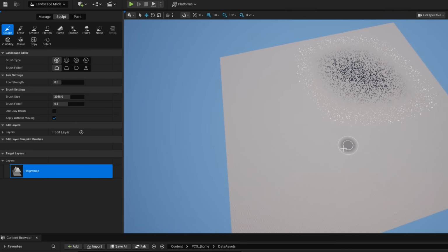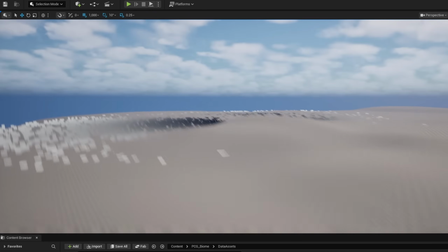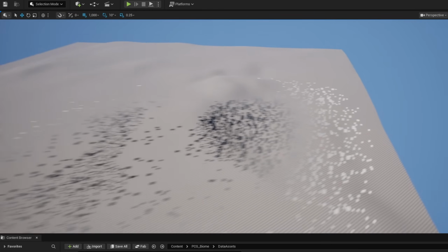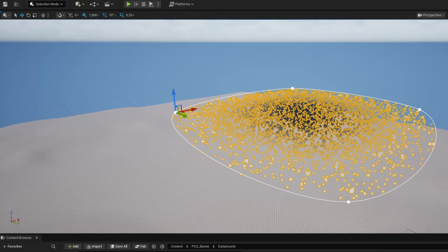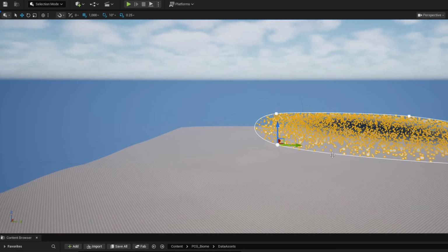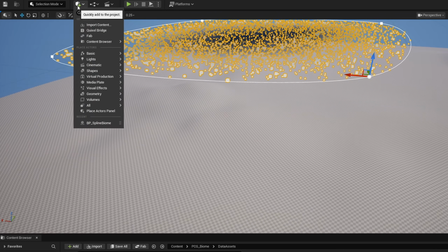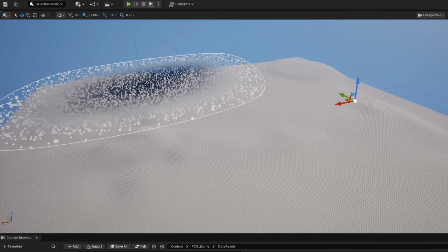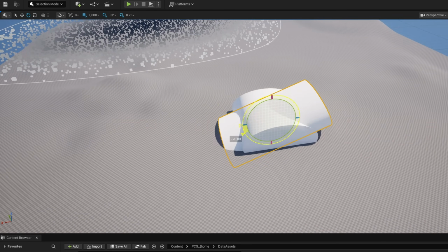And then I'm going to zoom out, and I'm just going to slightly warp this with some randomness here by using the sculpt. So we have uneven flooring here. So there we go. We have a little bit of hills, a little bit of flat areas. So now we want to have this spline project onto this landscape from anywhere up here. And we also want it to actually project onto meshes, not just this landscape. So in fact, I'll also add a basic cylinder here for demonstration. We'll go ahead and put it here, maybe add some more here so we can see what happens when we use regular objects.